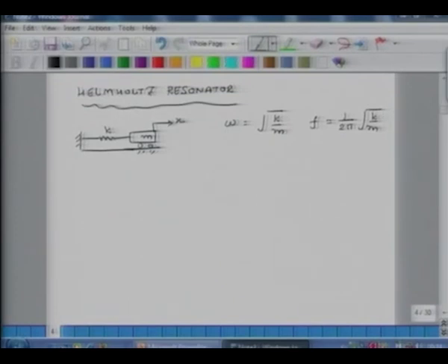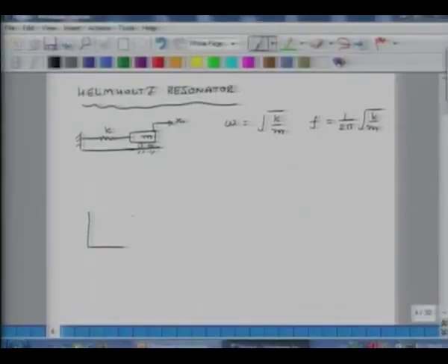You can have similar acoustic compliance systems in 1 degree of freedom in the area of acoustics. That is called a Helmholtz resonator, that particular device. Physically, what it looks like, in a very general sense, is you will have a volume and you will have a short tube.